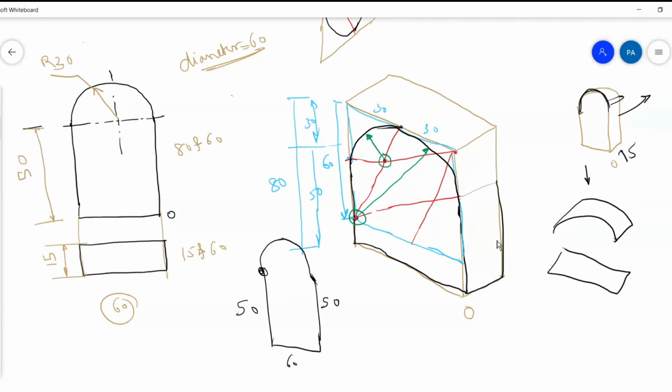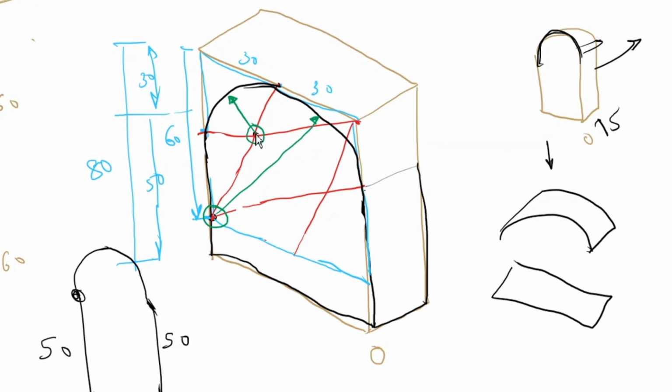This surface, you can see the one at the back, 15 mm away. But instead of repeating the same process of drawing the rhombus, finding the midpoints and then drawing this and this, what will we do? We will just move this center point from this point in this direction. Which direction? This direction, the right side. By what distance? 15. Okay, so see, I am now moving this center point.